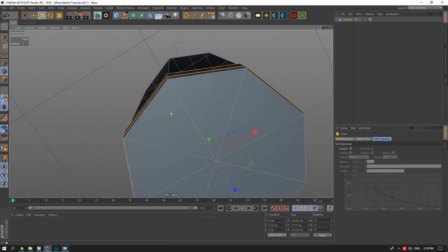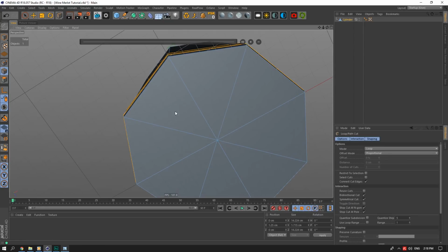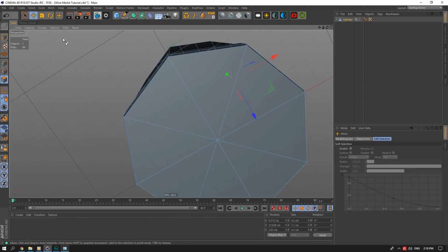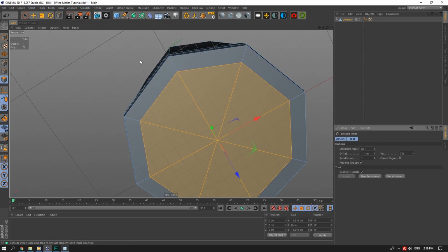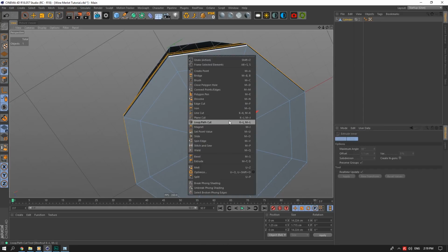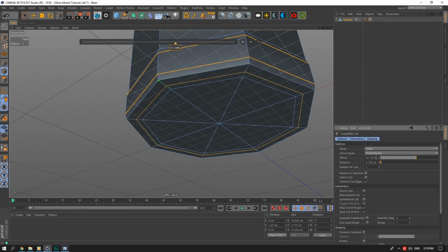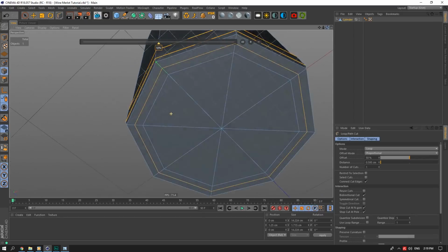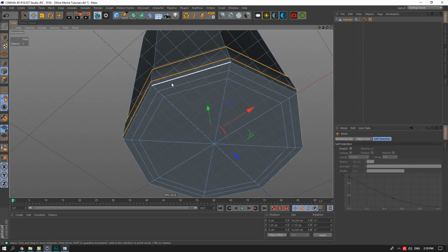If I look underneath the bottle, there's this little section that's around 1.1 centimeters in thickness. So the best is probably to take these faces here. Whoops. Take these faces here and extrude them in 1.1 centimeters like so. And then there's actually a point inside the middle here. If I just turn off the symmetrical cut, right there. So there's a curve that starts there and ends there. There's a curve that's about 1.1 centimeters in depth there.